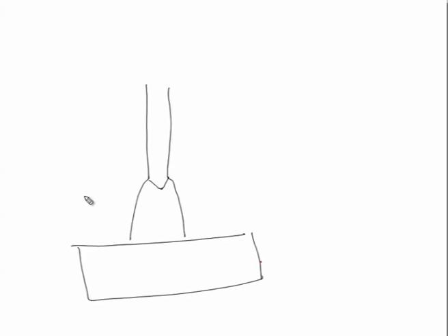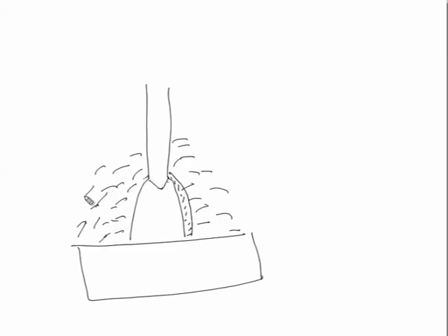To understand this, we will see this schematic diagram where we can see that this is the electrode and this is the welding arc, and this welding arc is completely covered by the flux all around. A very thin layer of the flux is brought to the molten state. So, this is the molten layer, a layer of the molten flux around the arc, and this is the arc zone, and here we have the weld pool.